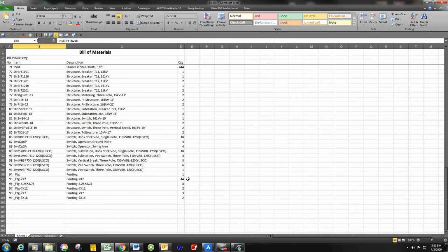And if you have some experience that tells you a typical depth, you could come over here and create a couple of cells that would break this out into its area, and then with the depth you could arrive at the volume of concrete, or at least an estimate of the volume of concrete, which then, when your foundation contractor comes in with their bid, you'll have something that you can at least measure against the amount of concrete that they are proposing for the project.